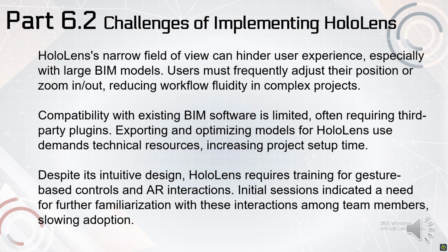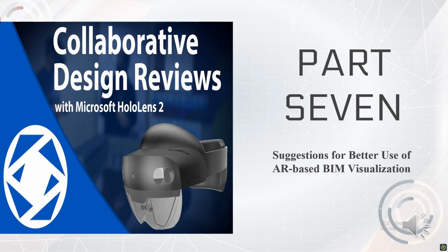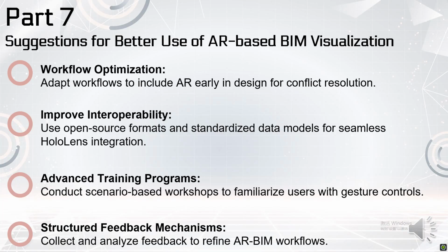The last part is about suggestions for better use of AR-based BIM visualization. The first is workflow optimization: adapt workflows to include AR early in design for conflict resolution. Then, improve interoperability: use open source formats and standardize the data models. Third is advanced training programs: conduct scenario-based workshops to familiarize users with gesture controls. And the last is structured feedback mechanisms: collect and analyze feedback to refine the AR/BIM workflows.